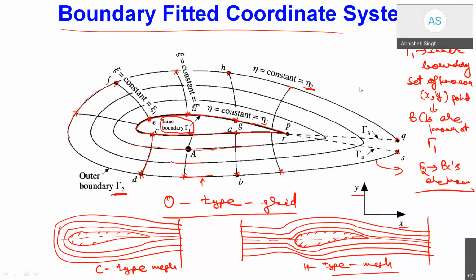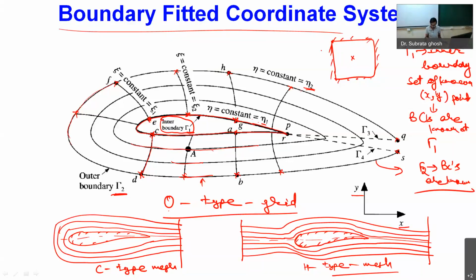The reason I say the nature will be elliptic is that in an elliptic physical situation, say this is my domain, we consider that if the boundary conditions for any field are known at all the boundaries, and I want to predict the value at any point within the domain, say temperature, I know here 50 degrees Celsius, here 100 degrees Celsius, here say 150, here say 250.